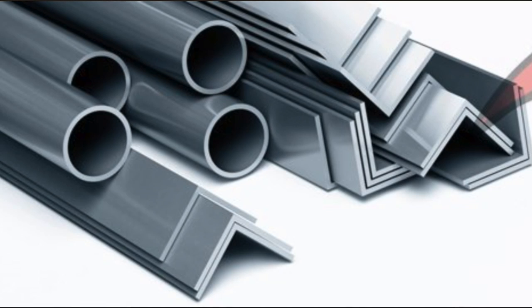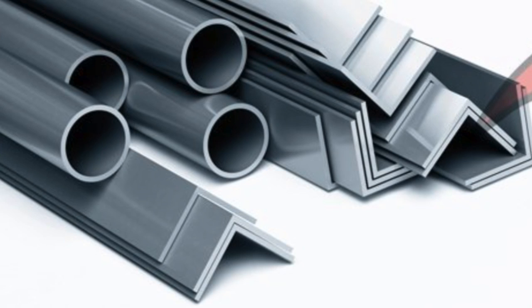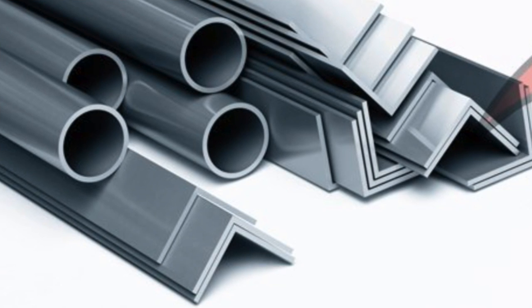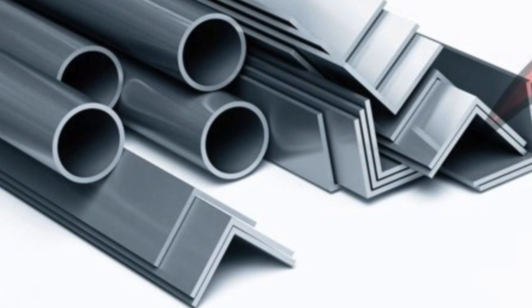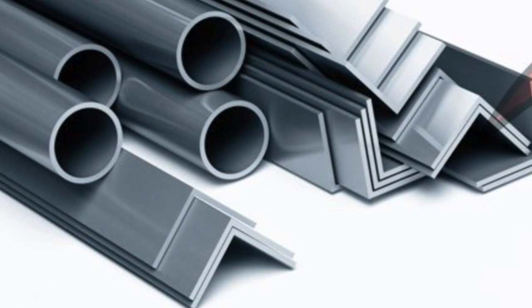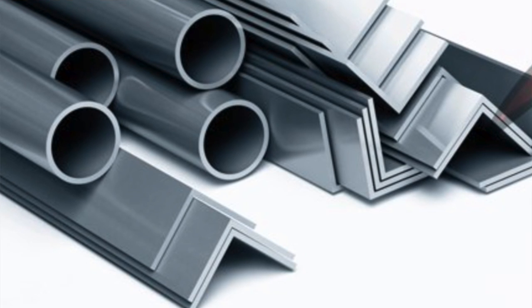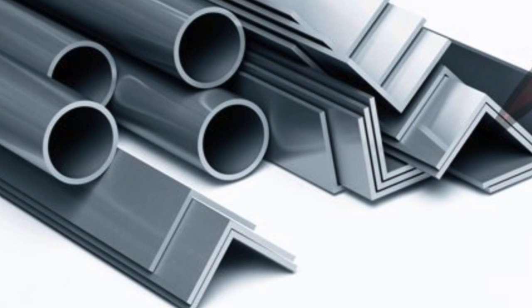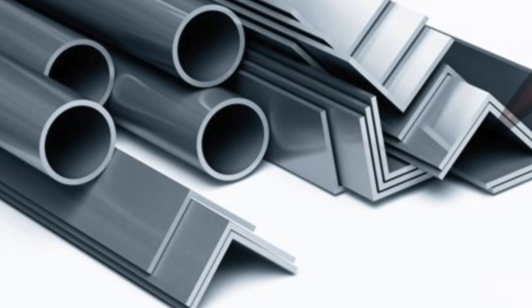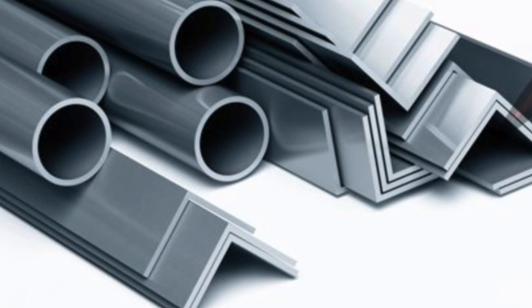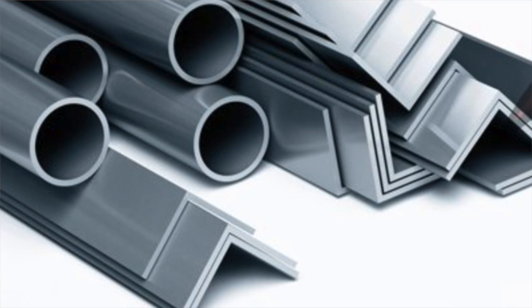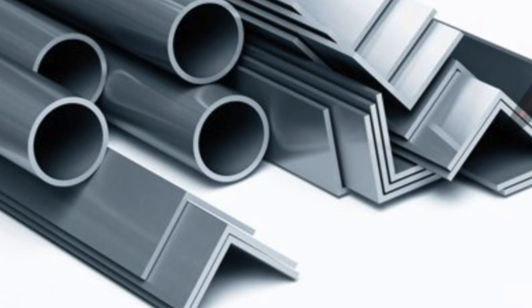To summarise, circular hollow section 60.3 by 3.6 was selected for the struts since it was in compression and its design capacity exceeds the critical compressive force found. The design selected is therefore safe to use. 50 by 50 by 3 equal angle, grade 300, was selected for the diagonal bracing for both the roof and walls. This was because its tensional design capacity exceeds the critical tensile force acting on it. Therefore, the diagonal bracing design selected is safe to use.